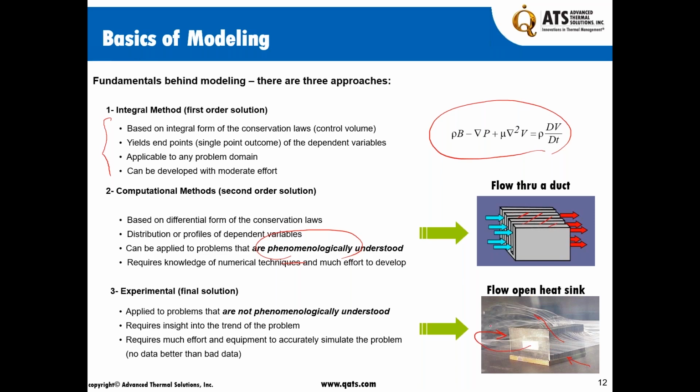It's a very, very complex problem domain, because you see the variety of flow regimes in the same control volume. If I put a control volume around this heat sink and try to analyze it, you can see how complex it is. In the one control volume, you have everything that's happening. So when we do the experimentation, it's typically gravitated towards the parts that we cannot really verify, or we use the experimentation for validation of a problem that we've done, either with an integral model or with numerical simulation.